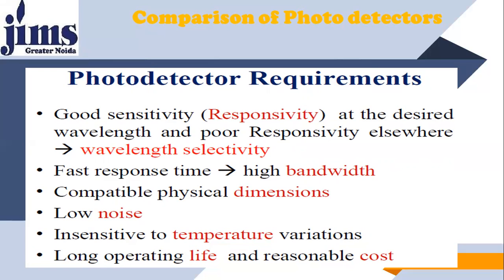Its sensitivity should be good, means its responsivity is to be good at the desired wavelength, and poor responsivity elsewhere. And the second thing that we want from photodetector is fast response time and high bandwidth, right?